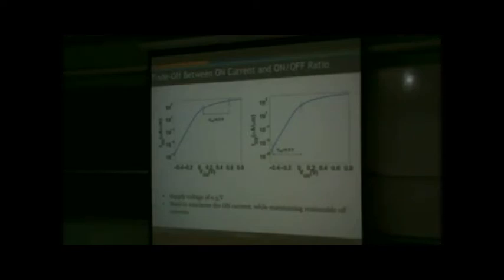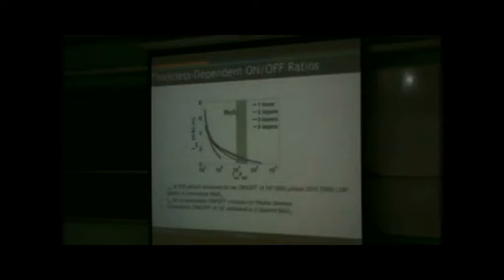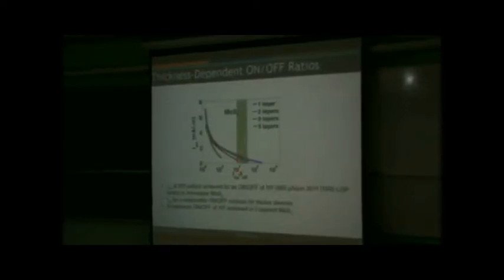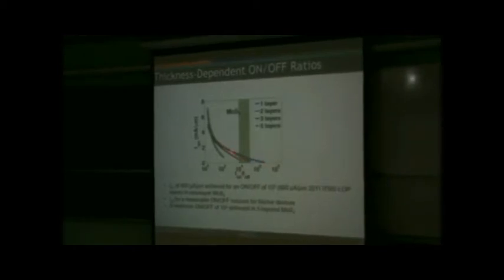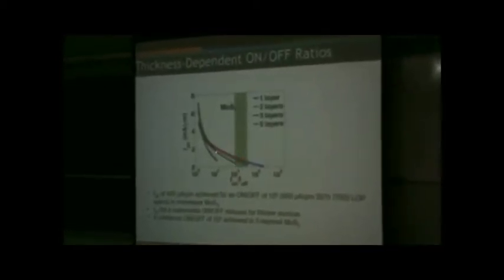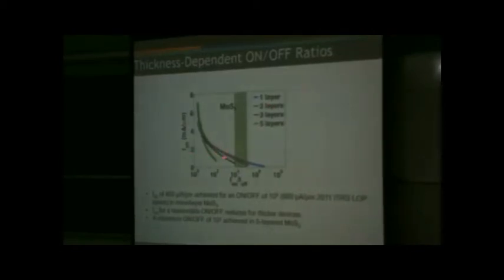We want to see how much ion we get for how much ioff. And you see, when I do that, this is for 10 raised to 5, right? You see, only monolayer and 2 layers can actually go there. As you go above it, they're very far from the 10 raised to 5. So the thing is, I'm not actually gaining anything by going above monolayers.